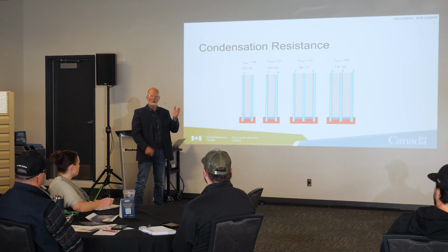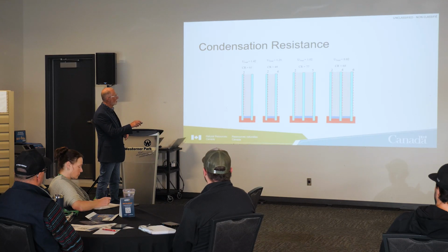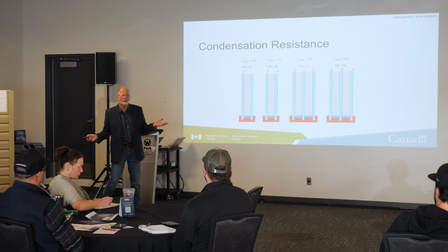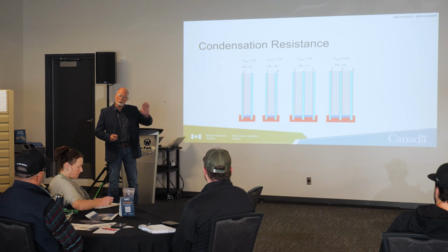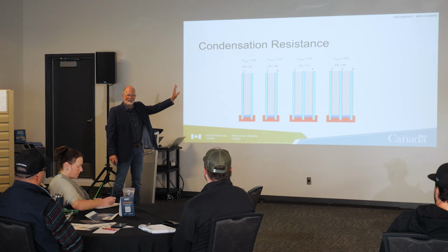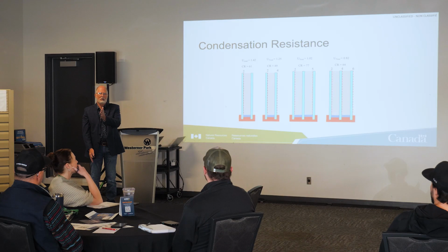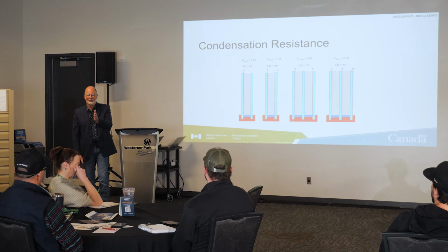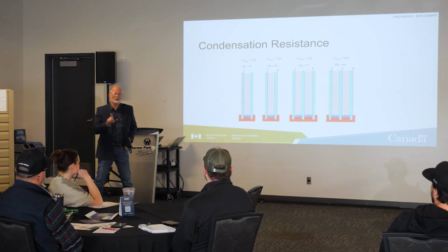How much heat is going to reach that window? The reason this one performs well is because it can absorb heat, but what if there's no heat there in the first place? So those factors do come into play, but don't rely on your window to be able to do that. If you take these two windows and move them inboard so that they're flush with the interior face of the drywall, you've reduced the condensation potential on that window. So that's a really good question.